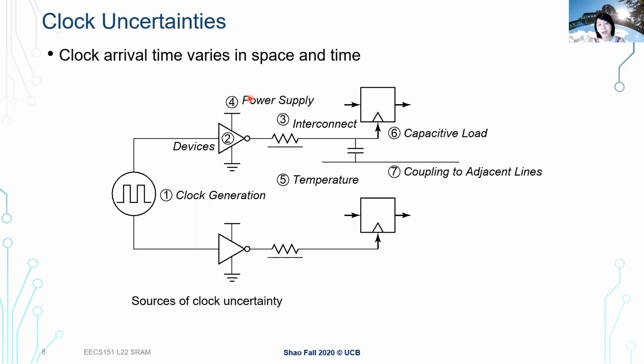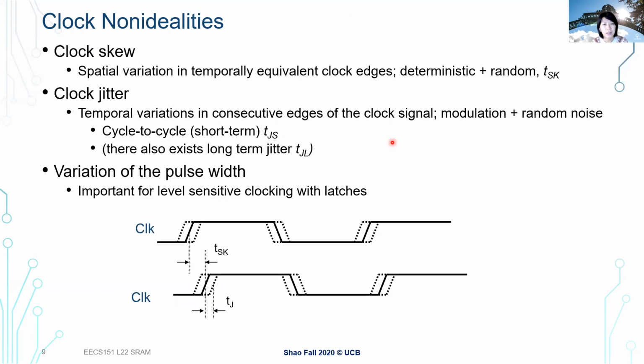So this is fairly high level. We're not asking you to analyze this or to quantify this, but at the same time, we should at least be aware. When you think about clock, it's easy to think of it as a very clean, beautiful signal that always rises perfectly, like the way we do simulation. But there are a lot of practical concerns when we think about how the clock is propagated to different flip-flops in our design.